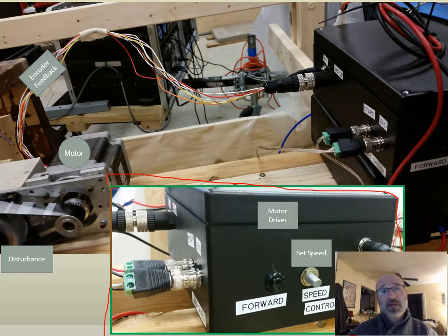Now this system contains our motor driver, our microcontroller, and our potentiometer to set the speed manually. So we can run this as an open loop or a closed loop system, depending on what we want to do. If we want to run it as an open loop system, we can simply turn this potentiometer to change our speeds and keep tweaking it by looking at the output and then changing the speed. That could take into account all of the disturbances we may be seeing on the system by manually controlling it with this potentiometer.